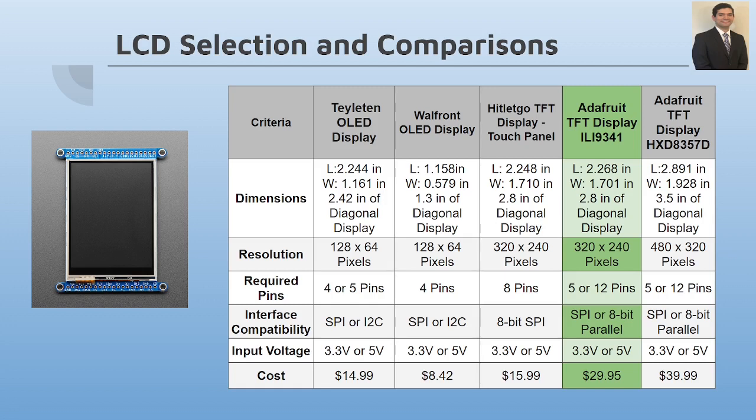It uses SPI as its interface, which is what we were aiming for. This is because SPI has a higher data transmission speed between the MCU and the display than the I2C interface. We needed this higher refresh rate to ensure that the graph of power over time was going to update accurately and in real time.